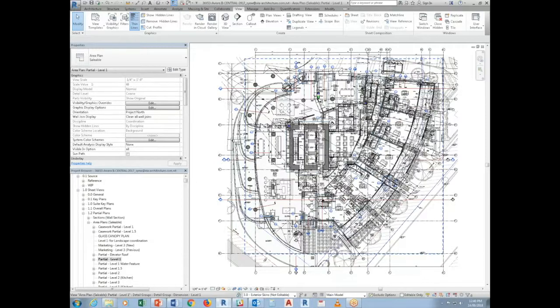If someone made a mistake, it's basically either going to be in the working view or the sheet view, right? The more views you put it in, sometimes the newer user just would not know where it is. They assume, I'm working on working views, I put all my tags there. You want me to dimension? They put it in working views. Sometimes people think this is the view that I have to work on, and people start dimensioning stuff, and then where's the dimension for the sheet view? It's like, I put it on my working view, so there's that big confusion going on. We want to eliminate that as much as possible. If it's possible, try to keep it as few as possible.